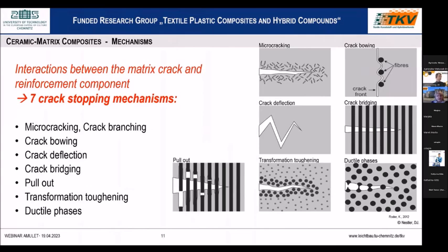All mechanisms aim to increase the fracture energy of a material through corresponding structural optimization. Since the specific surface energy is conditioned by the crystal structure and the direction of the cleavage surface, an increase can hardly be achieved there. It therefore remains to increase the fracture surface itself by deflecting a crack from its plane path perpendicular to the tensile stress.